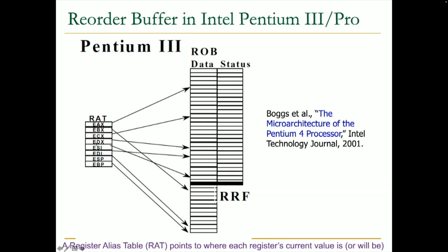This is the tags that I showed you. And these are the 8 registers. Basically, if an instruction is sourcing register 0, this is an index that tells you register 0 is in the architecture register file, or it's coming from reorder buffer entry X. So they basically separated the tags from the register file over here. But it's essentially the same concept.